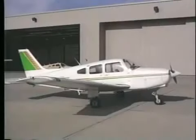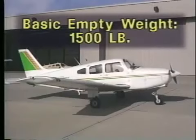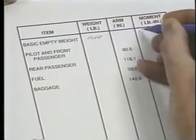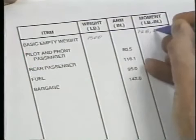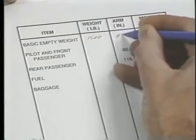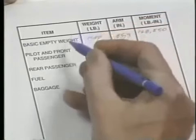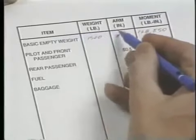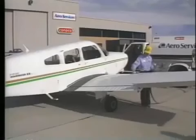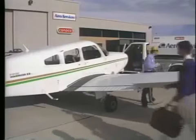For this problem, let's assume the basic empty weight is 1,500 pounds. This weight and its moment, along with its CG if given, is then transferred to a worksheet which contains 4 columns labeled as shown. You must then complete the weights and moments for the rest of the useful load.